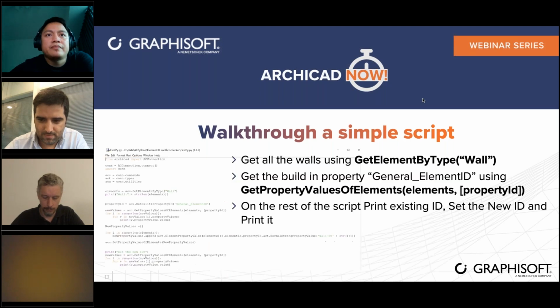So this is the plan. Get all walls using get element by type, for example, wall. You can get this command inside our documentation, the API Python wrapper. Okay, so the next step would be once we get the wall, we need to get the properties, for example, element ID. Then the rest of the steps would be more on printing or listing all the existing elements, and then list all the properties, and then set the new value. Okay, this is a very simple step that I think is a good step for you to start.